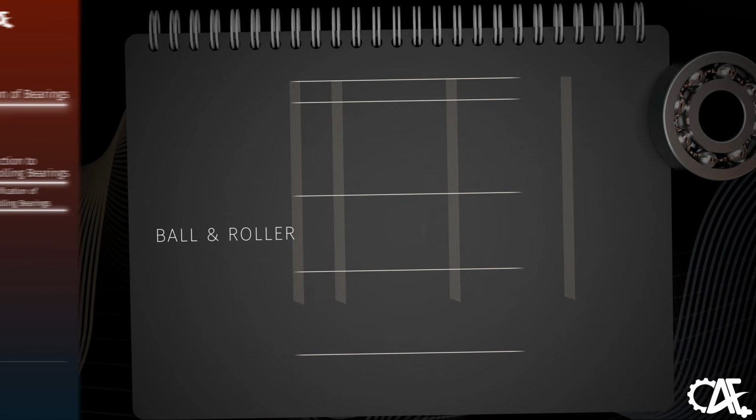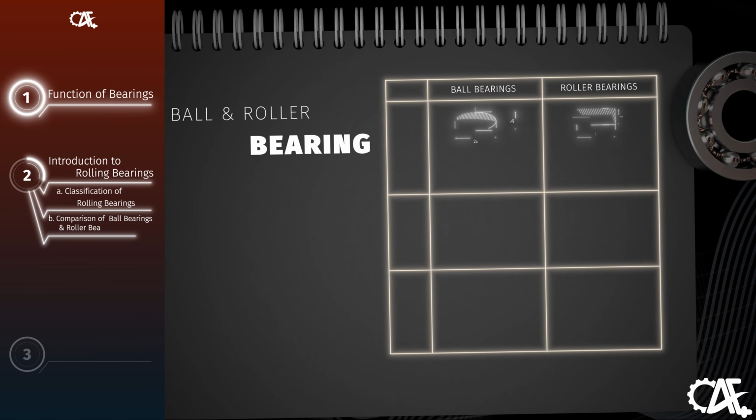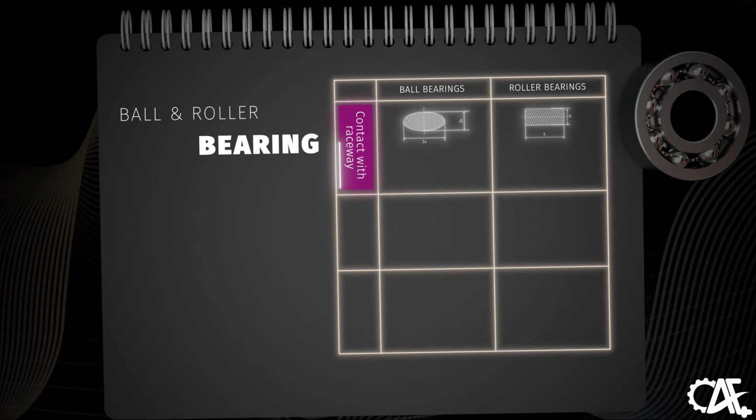Ball bearings and roller bearings differ fundamentally in their points of contact with the raceway, their inherent characteristics, and their load capacity. While ball bearings have point contact, roller bearings utilize line contact. Here we will explore their differences, beginning with their interaction with the raceway. When a load is applied to ball bearings, the contact surface takes on an oval shape. In contrast, roller bearings typically adopt a rectangular contact shape under similar load conditions.